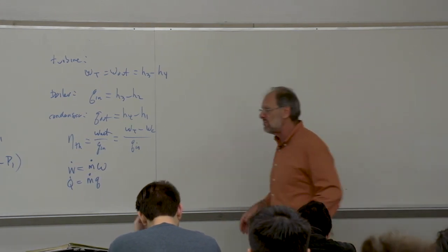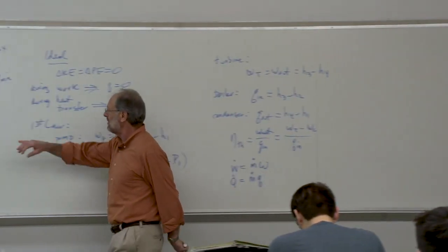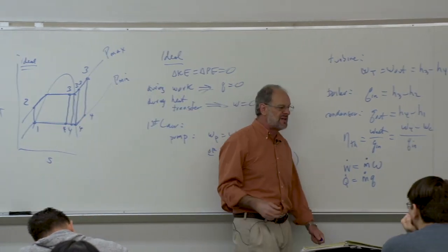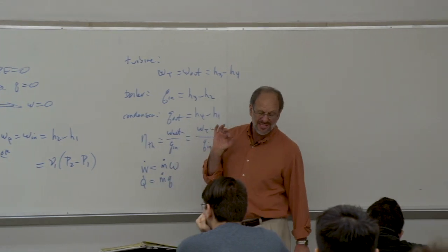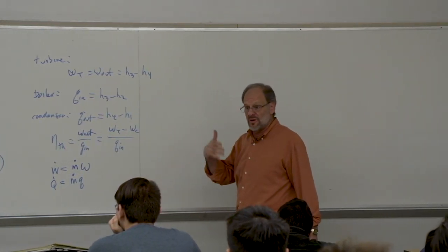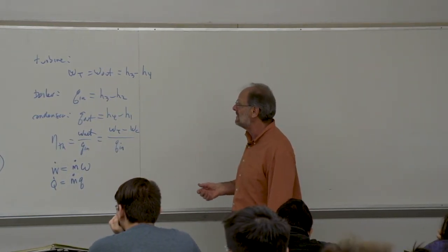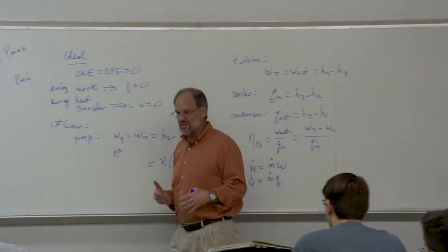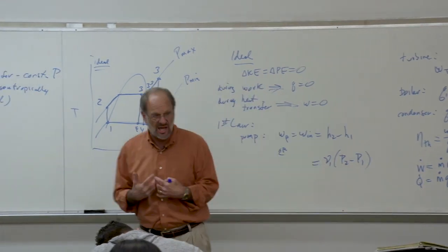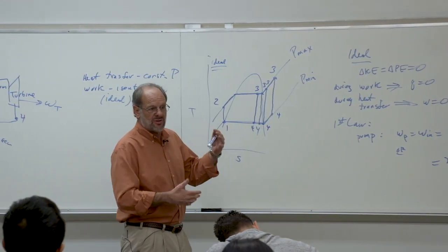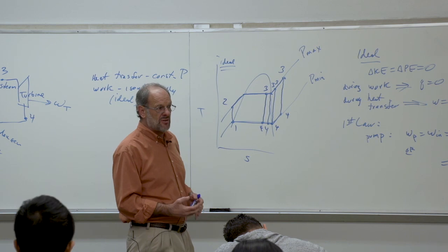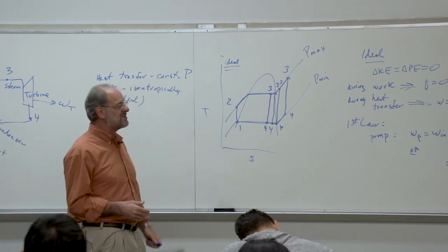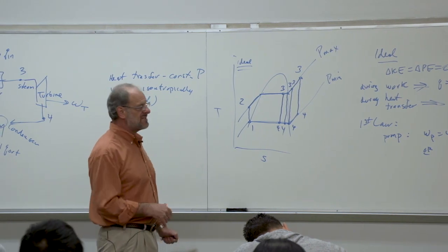Maybe I just want to remind you before I move forward that when we deal with an isentropic work process, whether it's compression from 1 to 2 or expansion from 3 to 4, we certainly treat this differently than we did when we were dealing with our gas power cycles. I mean, we're not going to use relative pressures anymore, or relative specific volumes. We're not going to use ideal gas equations that relate pressure and temperature and volume ratios. Those only apply to your ideal gas type problems, right? The ones where we have air standard cycles to model our gas power cycles.